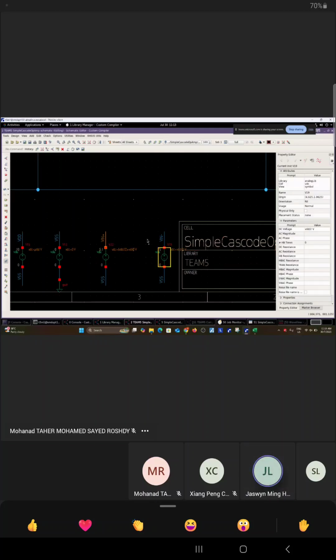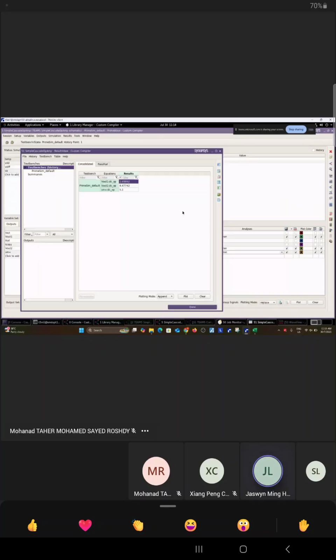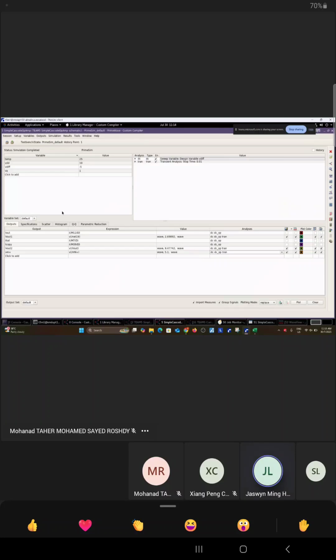That's fine already. So right now we go to the simulation. By setting up this, you don't have to change the connection. We just say VDD over 2 plus VDIF instead of reconnecting everything. Put a VDIF in the middle. We sweep it the same way. You run again.